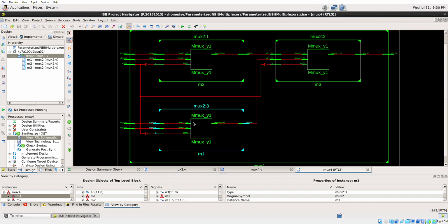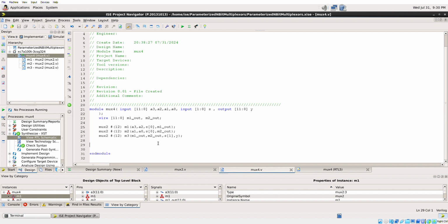So now you may provide a 12-bit input or an n-bit input also. This is how we create parametric modules in Verilog. You may create other modules also using parameters. That will also help designers to debug circuits easily.